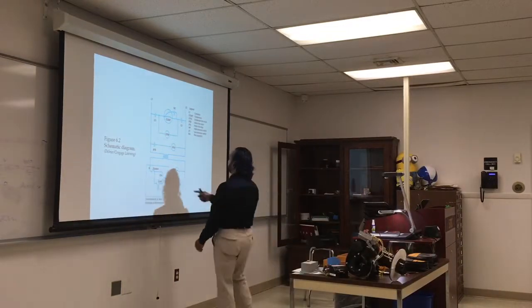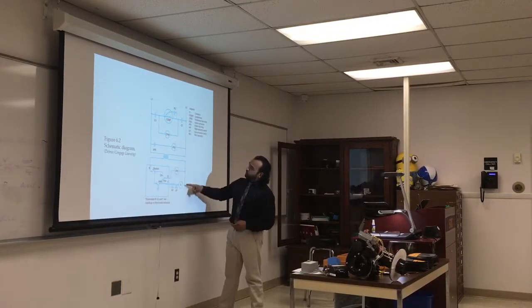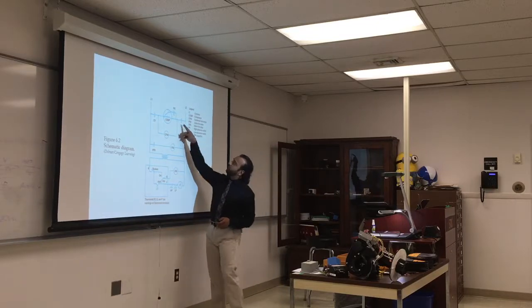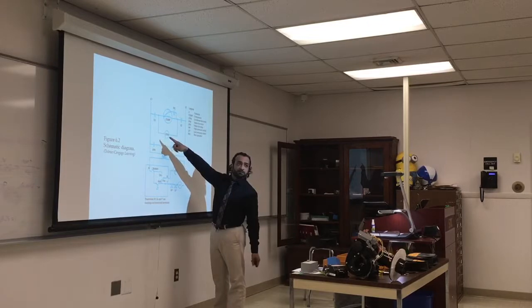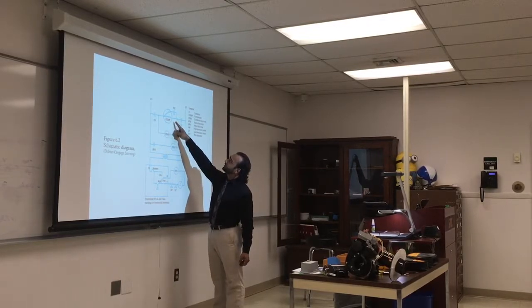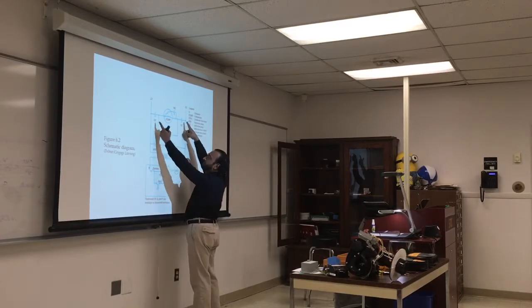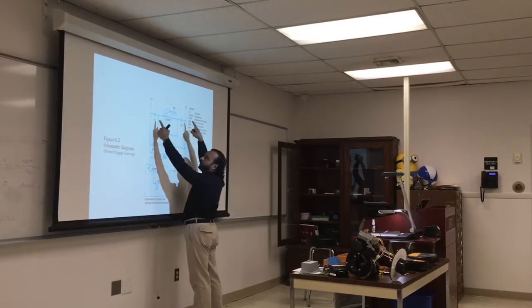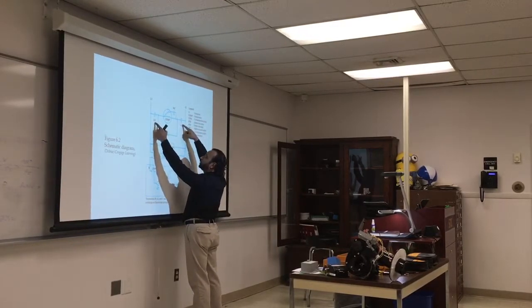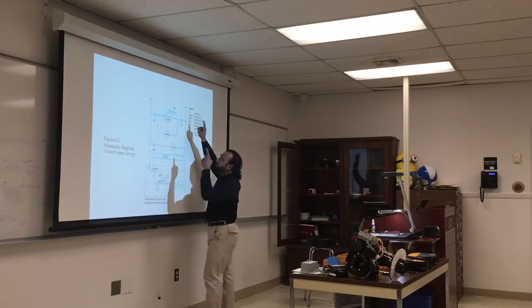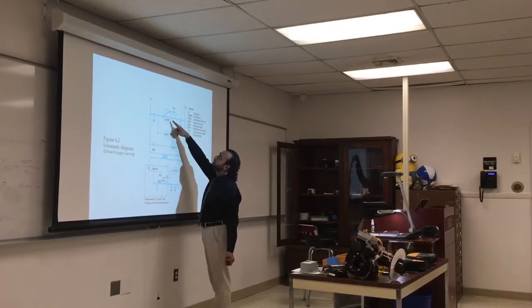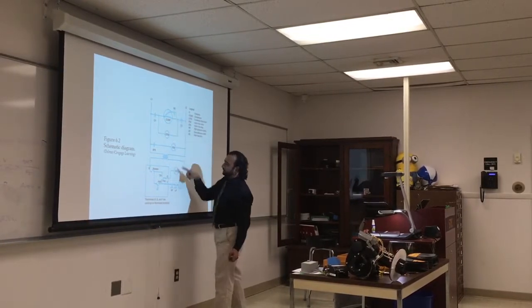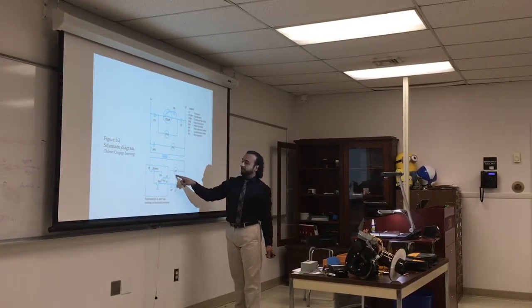So, and this is a contactor. If you look here, we have C1 and C2, which are contactors that will turn on the compressor over here, and here is the relay contactor. So once we turn on the power, these are the two types of the contactor that will cut off both the hot and neutral, isolating the compressor. But once we turn it on, these should be closed, and the compressor should turn on when the relay turns on. What controls the relay?